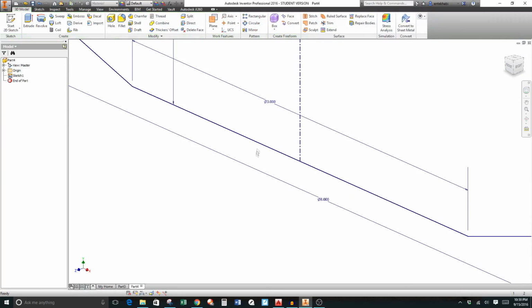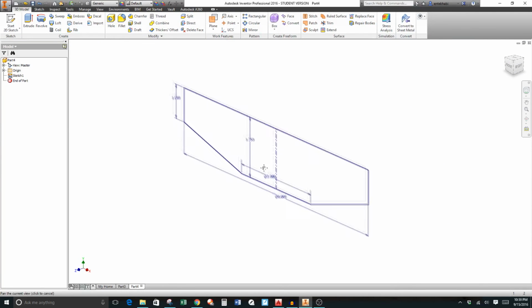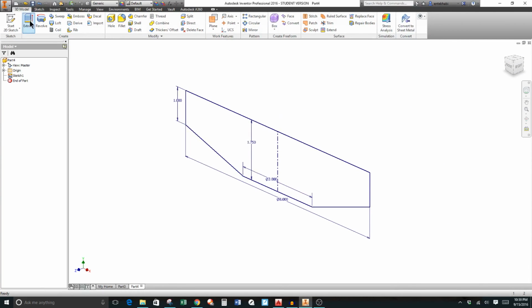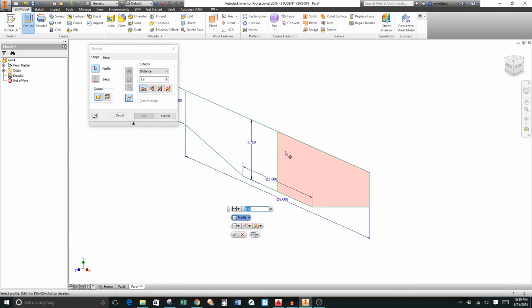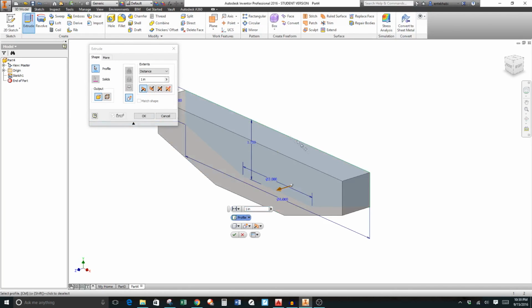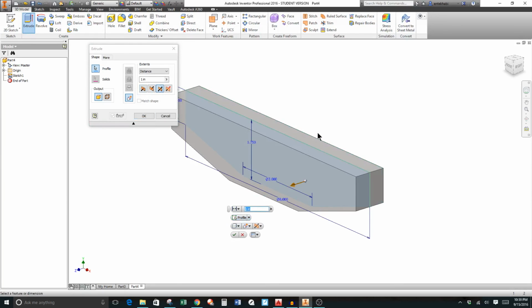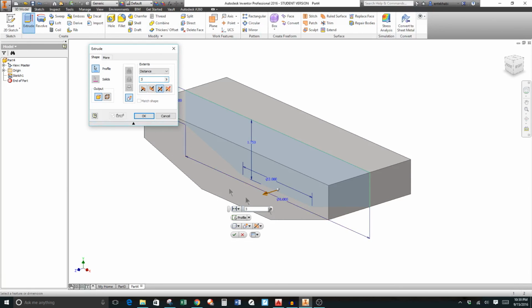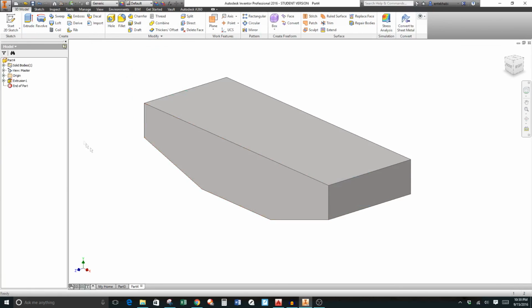mirror is done. Finish the sketch, and then we need to extrude this in both directions, and this gives us our first model feature, first base feature. So again, we are extruding in both directions, a symmetric extrusion that helps us in creating the future sketches.